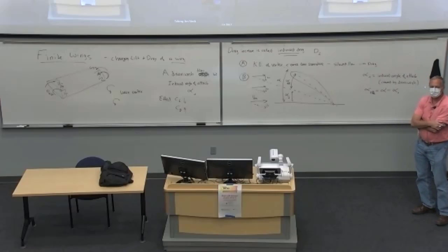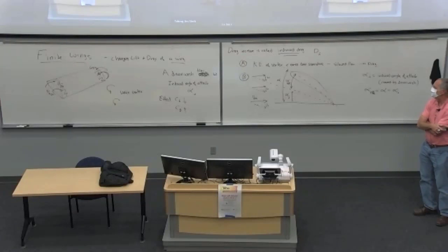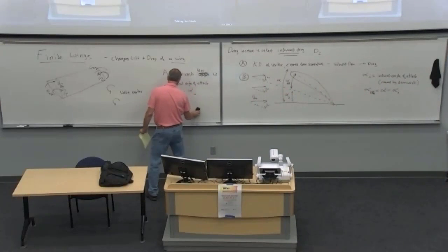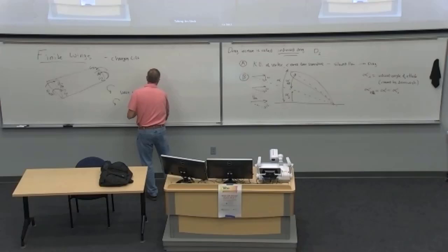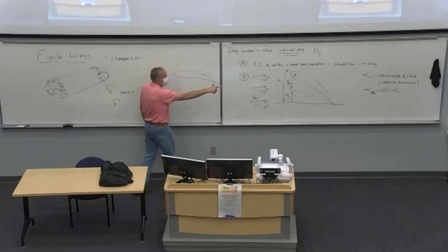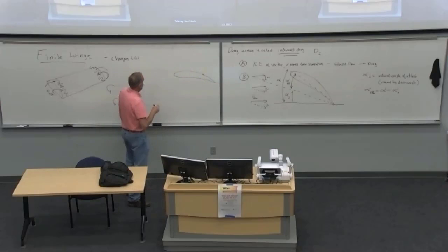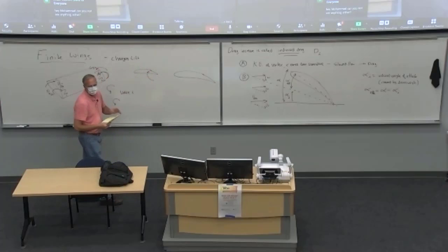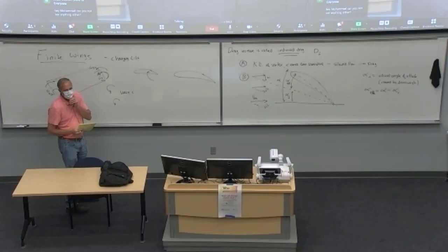Yeah, and we call that upwash because it's not down, it's up. But yeah, if you get upwash from some other reason, it would increase the angle of attack. And in fact, for canard airplanes, one way to model the canard is to say there's upwash caused by the wing. So a big wing back here, and instead of having a horizontal tail in the back, which gets hit by the downwash, you would look at a canard up front and you'd say, well, there's some upwash hitting that. So that is a legitimate way that people model that effect.